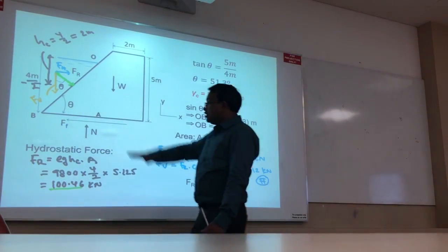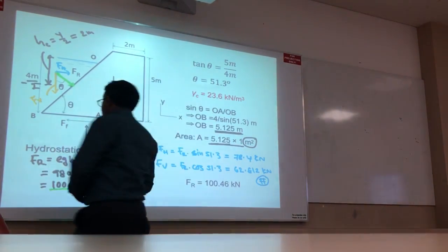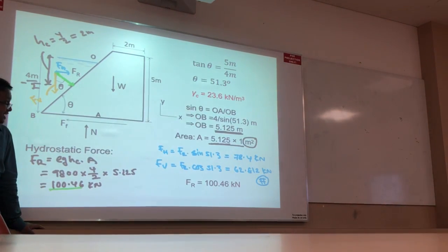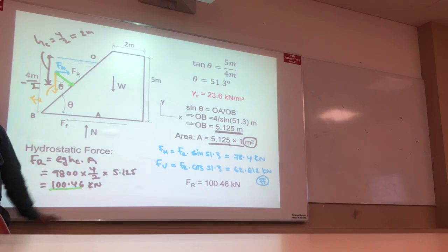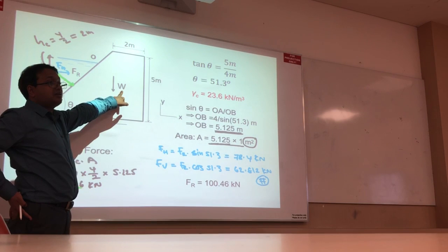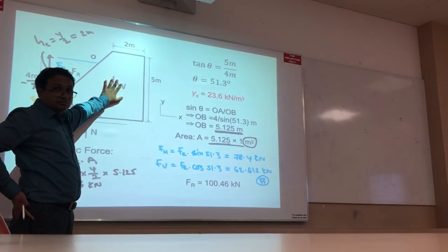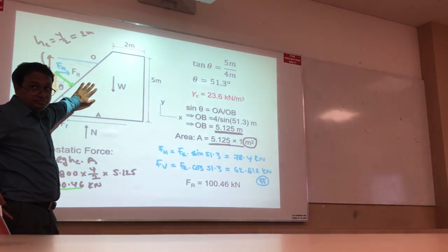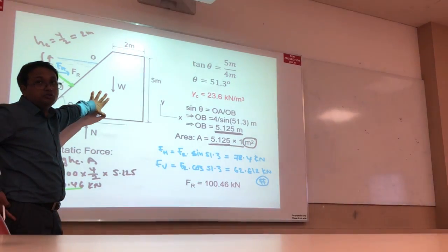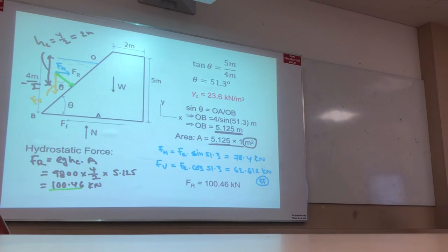Second part they tell you to find the coefficient of friction. Then in that case, you have to do the force balance both in x-axis and y-axis. Right? So W you have to find. What is this? Weight of the block. So this value is equivalent to rho g times volume. You know, right? So what is mg?